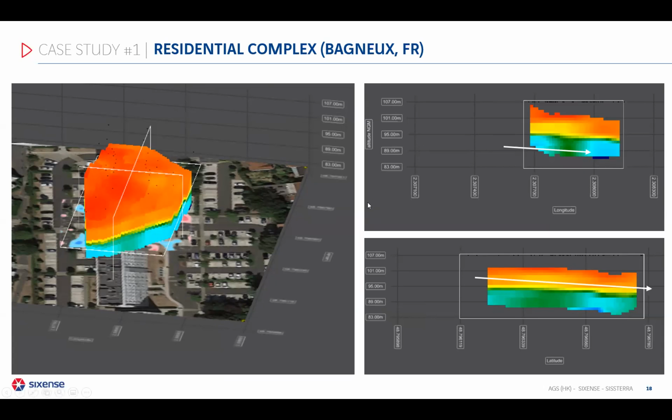This information is relatively simple, but it was reinforcing the assumption that cracks were coming from differential settlements, as the thickness of the compressible superficial layers that show low shear strength is varying below the building. So after this survey, after this 3D evaluation of the shear strength of the materials, it was proposed to drill a few boreholes to calibrate the seismic velocities. You can move to the next slide.